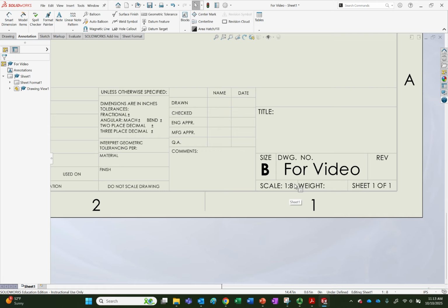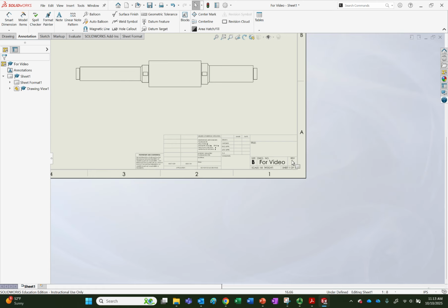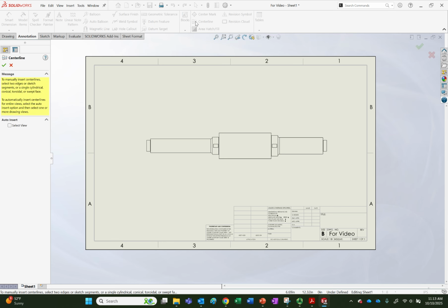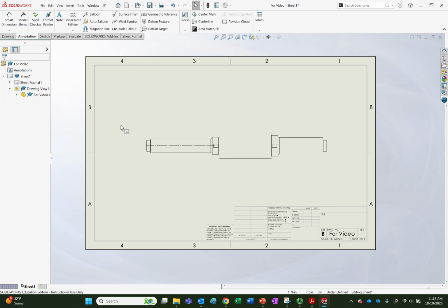But by the way, it didn't change it down here. We changed it there, but we could also have changed what the sheet scale was, I think. I don't remember, actually. I haven't done it in a while, but I bet we did. But let's make sure we fix that to make that accurate. And now we're going to start to do the dimensioning portion of this. I think if something's round, you need to use the center line. So we pick that center line and pick that guy right there. And you only need one because you could stretch him. All right, so we stretch him all the way through. That tells everybody this thing is round, right?